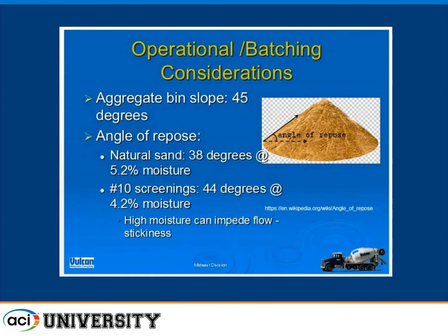It's not all angle of repose in terms of movement through the bins and in batching, because the number 200 mineral filler also creates some stickiness to the material. So the batchman will be calling for 450 or 800 pounds of number 10 screening, and the material is not falling. It's problematic.